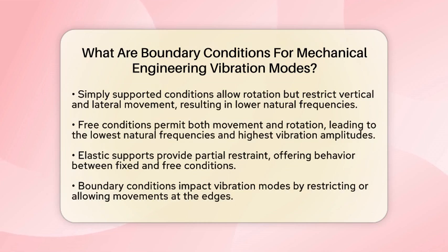Then there is the free condition. With this setup, the edge is completely unconstrained. This means both movement and rotation are allowed, resulting in the lowest natural frequencies and the largest vibration amplitudes.